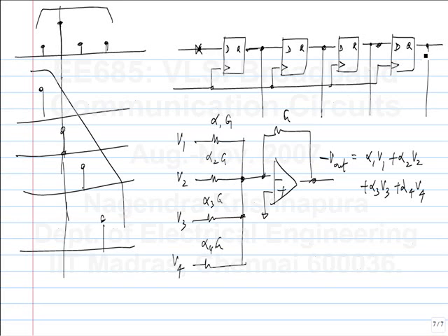Okay, let's take a concrete example. You've all been working with 1 gigabits per second data in your assignments. What kind of an op-amp would you need to do this? What are the figures of merit of an op-amp? Most important one is the unity gain frequency. What should be the unity gain frequency of this op-amp? I mean, just guess wildly, what would be the unity gain frequency? It's definitely greater than 1 gigahertz. How would you decide exactly how much it is?